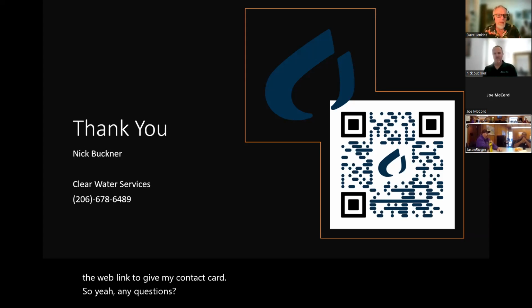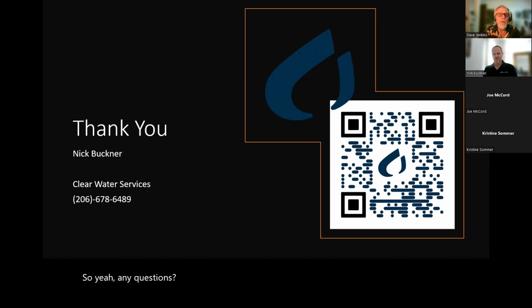Hey, Dave. Christine. There's also a consideration. I know we worked on those port projects together. If you're doing early design, understand what other products the contractor is using that might have potential conflicts with different chemicals, different flocculants, different chemistries. Because I know we experienced that ourselves at Port of Seattle, just a general organic influence. And I know that happens on other construction sites, but if there is a possibility in early design to actually get an understanding of the full construction scope, not just the water treatment scope.